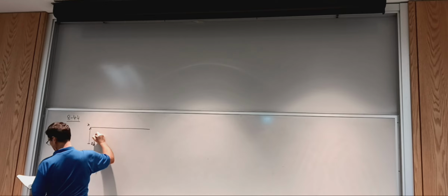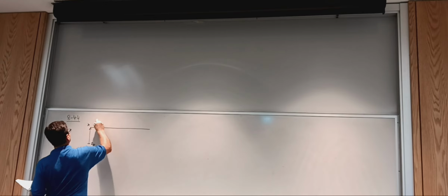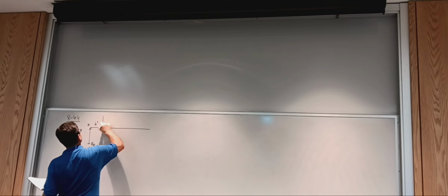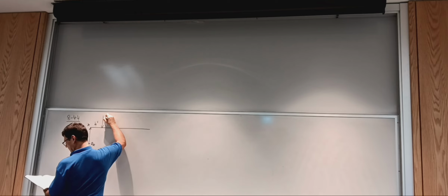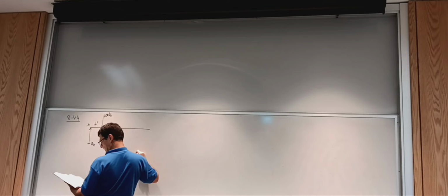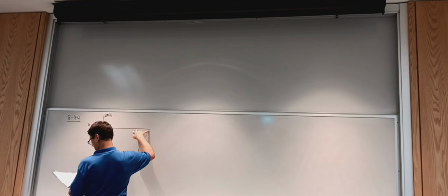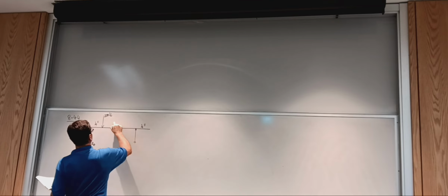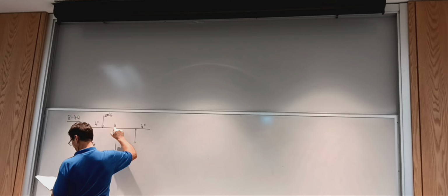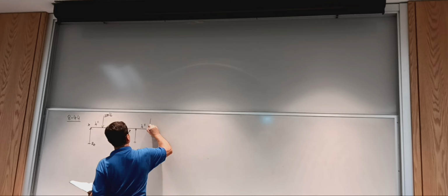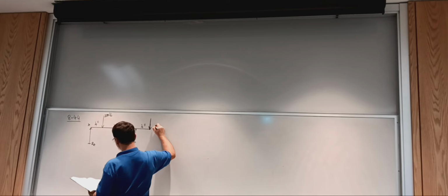We label this as A, and then I have 4 inches. There's geometric symmetry, but no load symmetry. So we have a 2,500 pound force, and then another support 4 inches from the end. There's an overhang, and this is 4 inches. In between I have 10 inches, and at this end, I have a down force that is 800 pounds.